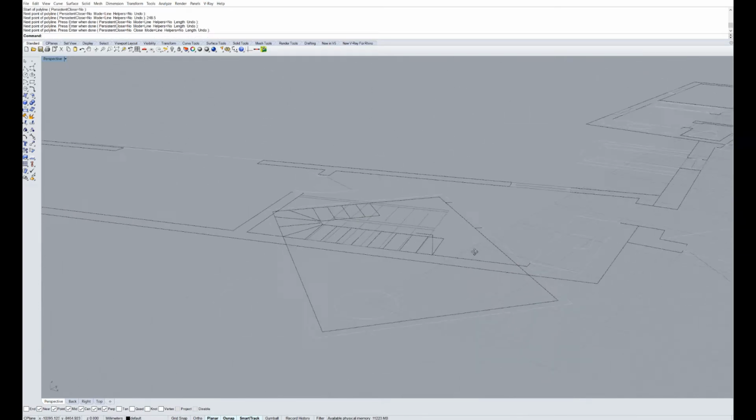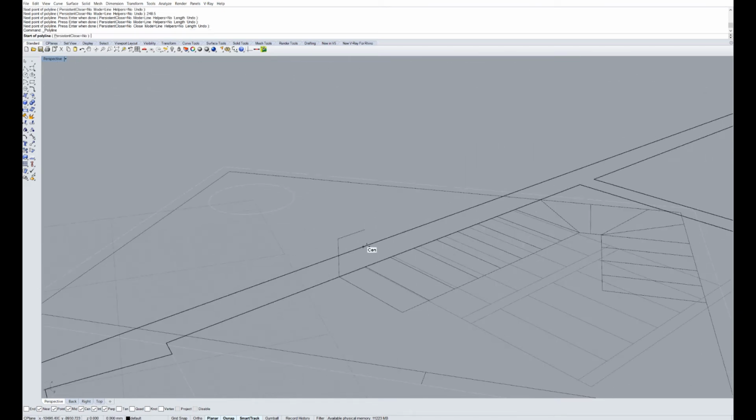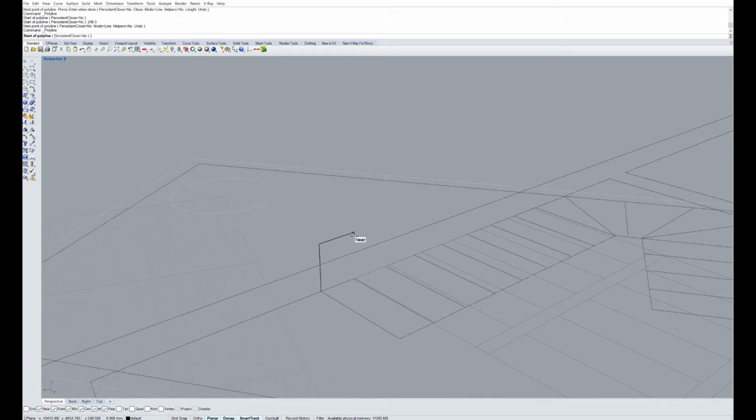So this is my first step. I built it by holding on to Control, moving it up, and typing in 248.5. Well, sorry, first you have to click the first point, which is going to be at the ground here, or wherever you start.